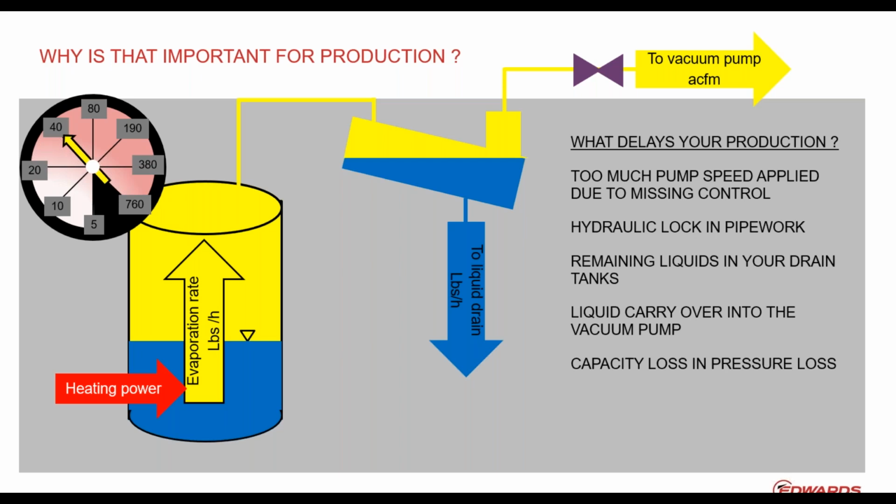The reason why the pressure is going down is not because you have such a massive vacuum pump going. The reason can only be you cool down the temperature of your liquid in your reactor and eventually even freeze it, because the evaporation rate is just on the surface of the reactor.